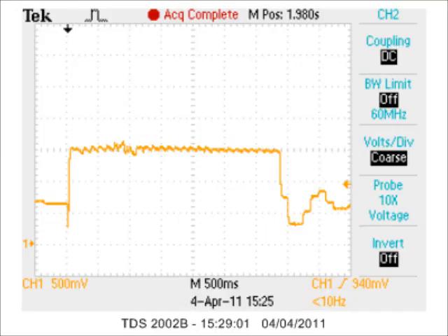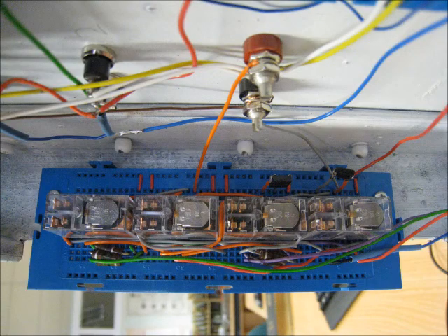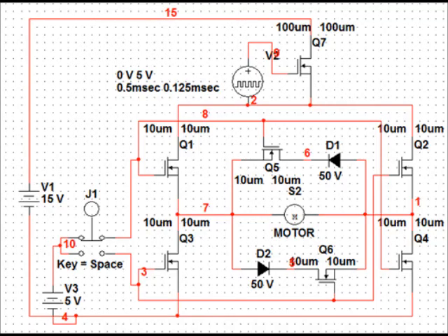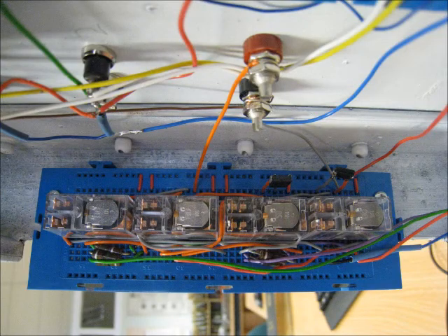Here you can see the limited current during the change in direction. There the motor is accelerated with maximum power all the time. These are the circuits to enable the change in direction. I was thinking about a semiconductor solution, but the source voltage is changing due to the PWM controlled motor supply voltage, so MOSFETs are quite difficult to control. Thus I have chosen a solution based on relays, which can be seen here.